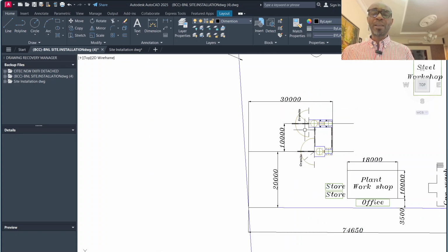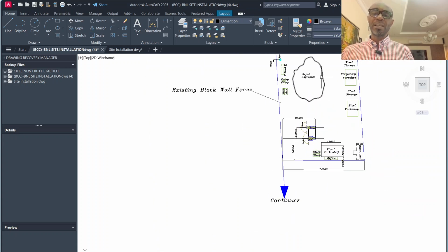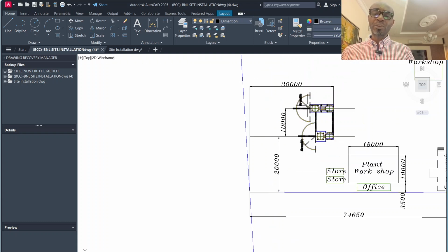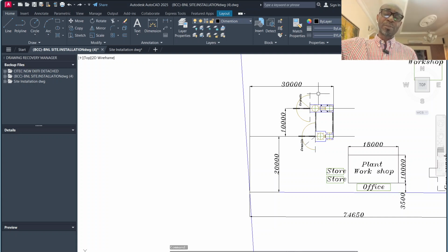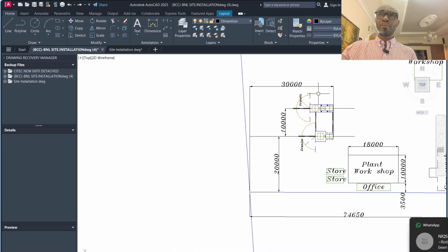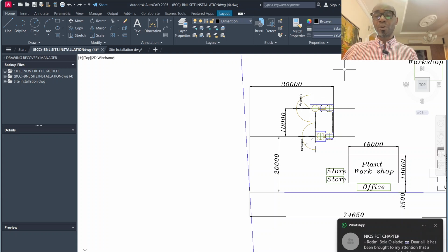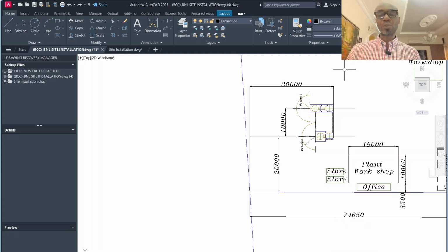Self-refilled batching plant where the payloader comes to this place, fetches the sand, fetches the granite, brings it close here. There are automated shovels that revolve around. It's like smaller shovels that scoop the granite, take it and drop it into the drop. And after it gets to whatever the weight is, it will stop.